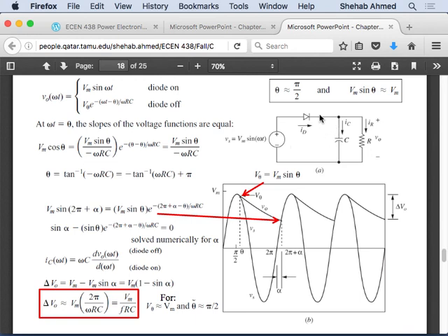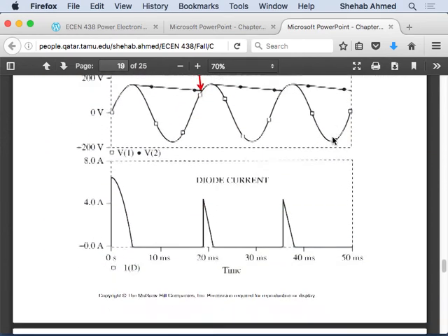Because now you have inductor in series with a capacitor and parallel with the resistance, versus inductor in series with a parallel combination of an R and C. If you have an inductor in series, you will not be able to maintain a certain specific output voltage. I don't know, I have to look at the equations here. But the output voltage, capacitors maintain voltage, right? Maintain a specific average value for voltage. Inductors, they maintain average voltage of 0. So we would have to look at the equations here.